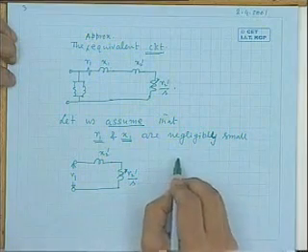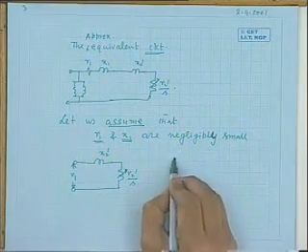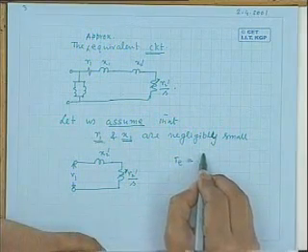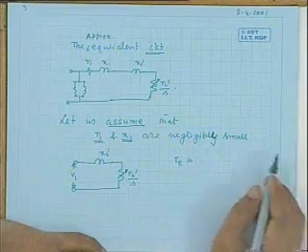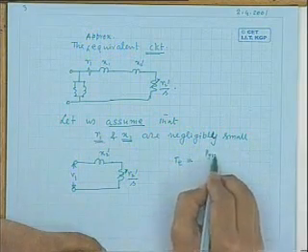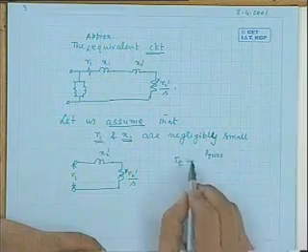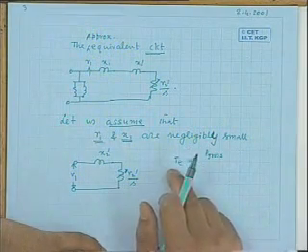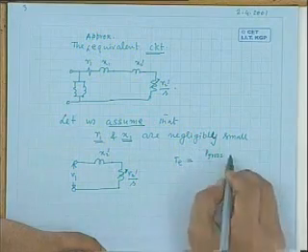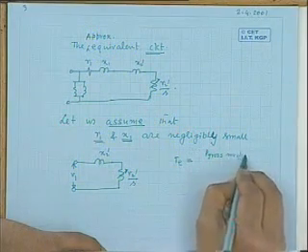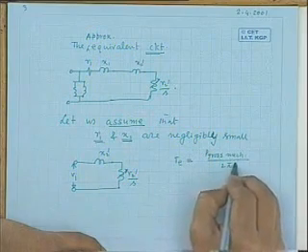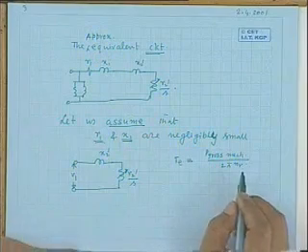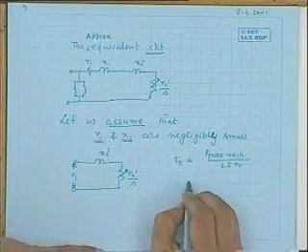How? The torque developed by the machine, we have seen last time, is the gross mechanical power output divided by speed. The gross torque developed will be equal to the electromagnetic torque developed by the machine. So electromagnetic torque is P gross mechanical by 2 pi Nr, where Nr is the actual rotor speed in mechanical terms.